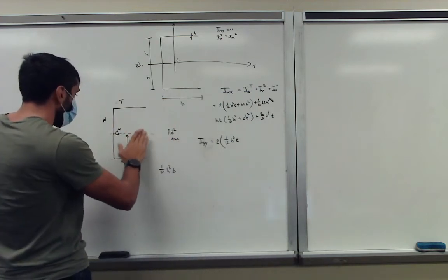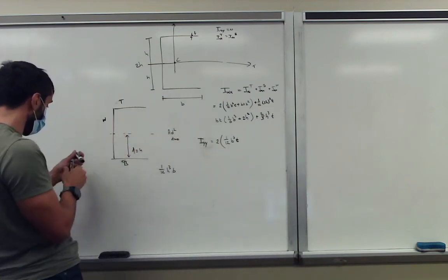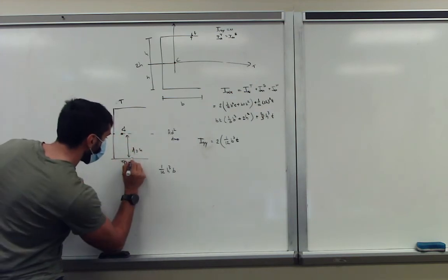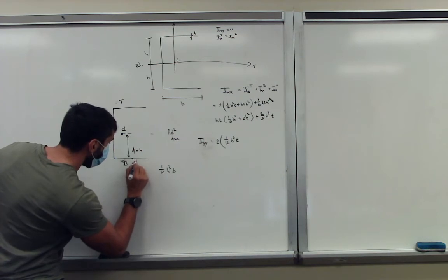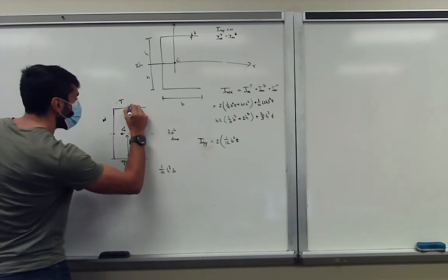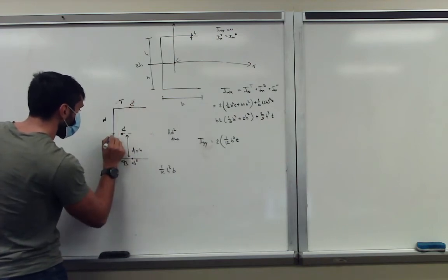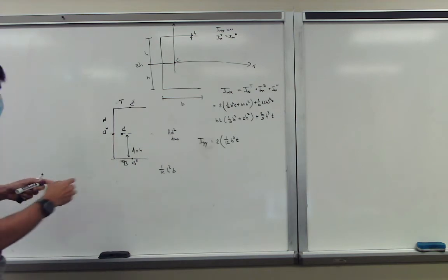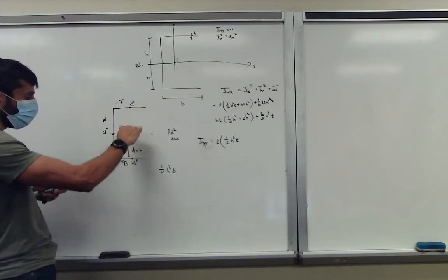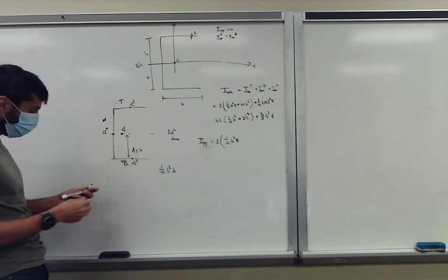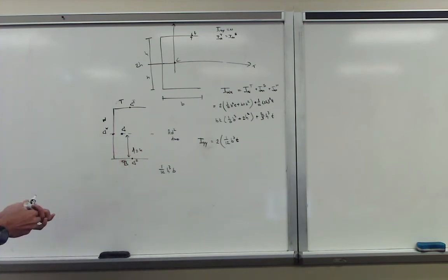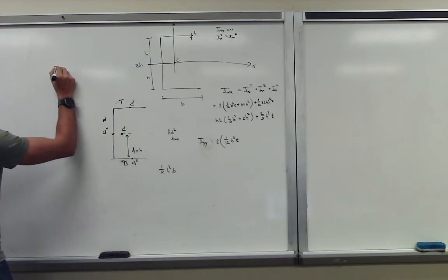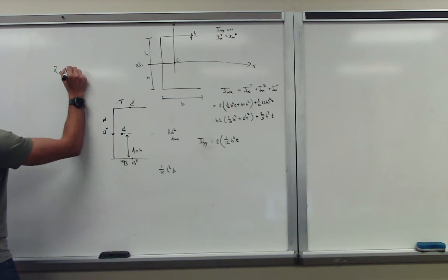Let's do it a bit more accurate. The centroid of the cross section lies here, and the centroid of the bottom lies there, and this is the centroid of the top, and this is the centroid of the web, right? So we're now not looking at the vertical axis, but we're looking basically in the x direction. So technically, you have to calculate the x coordinate of your centroid.